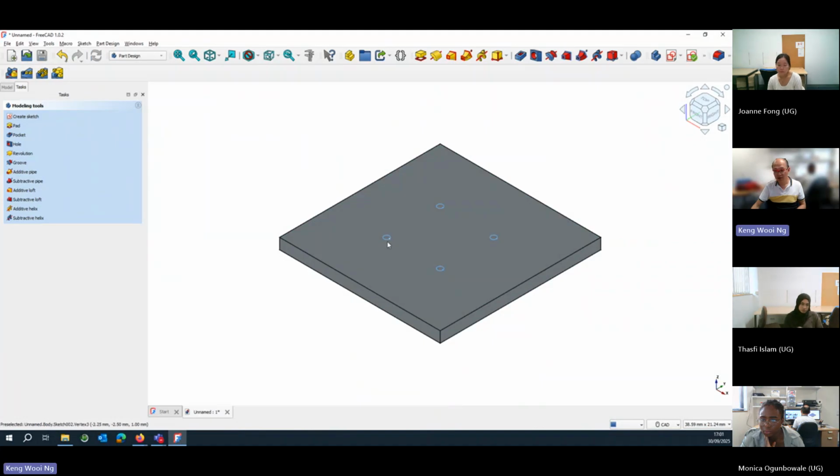We want to build up a cone, right, from this. There are other ways to do this. I'm not 100% well versed in this yet. A cone is kind of tricky to me to build. What I can build very easily is cylinders. To build cylinders, basically what you need to do is pad the circles, create thickness, and then we'll have your cylinders, right? So let's do that, and then from there we can get to a cone.